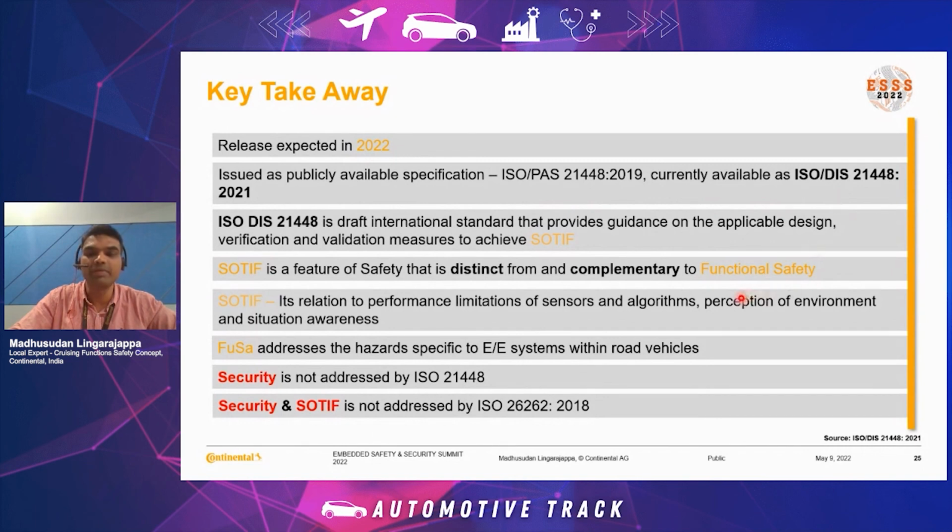This is a complementary specification to the ISO 26262 functional safety standard, and SOTIF tries to address hazards caused by external environmental conditions or by any misuse by users or drivers, which may lead to performance limitations in the sensors.